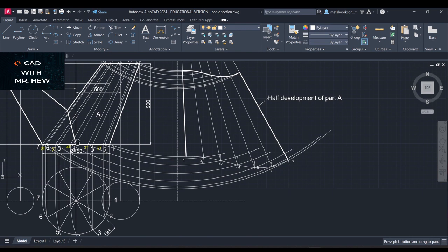Remember, you see this, what happened? This development right here would be the development without this cut piece here. So this development would not incorporate this cut. So to get that cut, just like how the top you transfer it over, so 7, you'd have to mark an arc coming around to 7 up here. So let me show you. The same as you did at the top, you're gonna do for this piece.